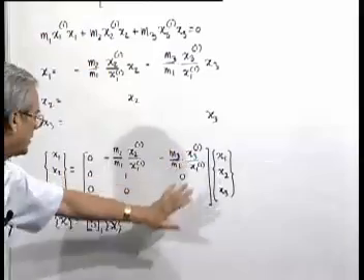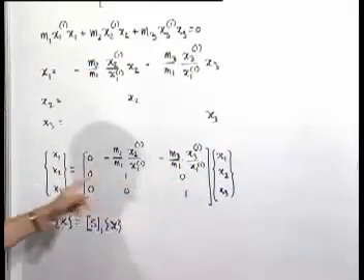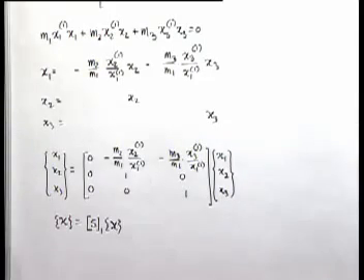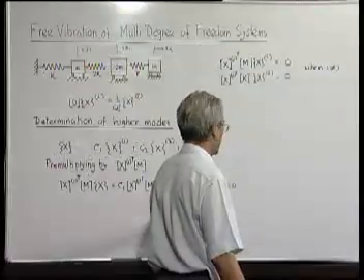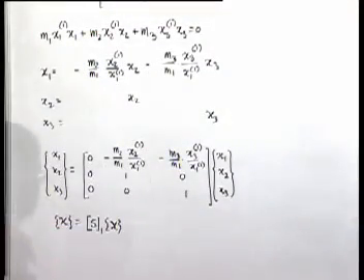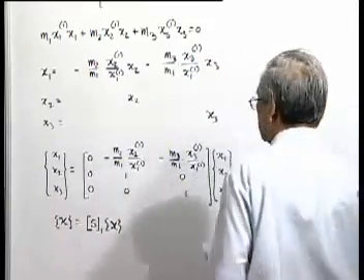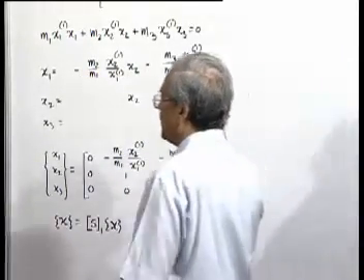So this is a known matrix. And when this matrix pre-multiplies this, it means that the first mode has been swept out, as C1 has been made 0. That's why we call it a sweeping matrix. Similarly, C2 can be made 0 by pre-multiplying